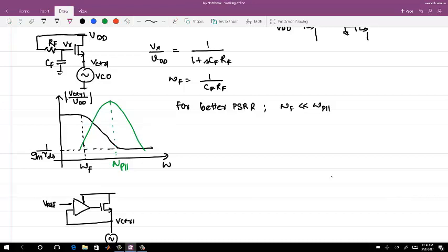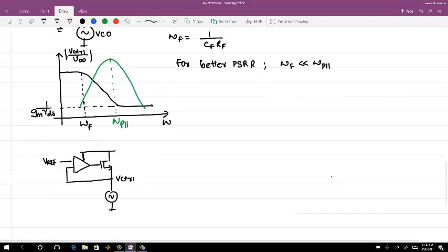But you see that at low frequency you are getting a gain. Looking at the previous regulator, I am getting a lesser gain at a lower frequency, but a peaking at a higher frequency. And here I am having a suppression at a higher frequency, but a finite or larger gain at DC. If I want to have both DC and high frequency benefits, what shall I try?